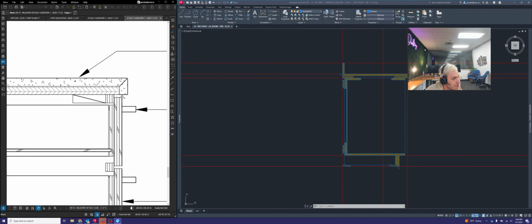So because we know that now, currently our cabinet is drawn where these white dots for the front of the drawer are in line with that countertop. We need to adjust the cabinet depth so that we can get that 1/2 inch gap. So we'll make our cabinet 23.5 instead of 24 inches deep, which should give us that little gap that we need right there.